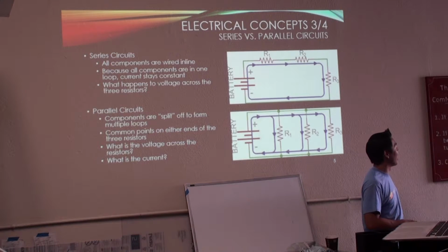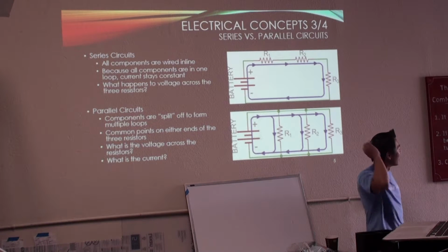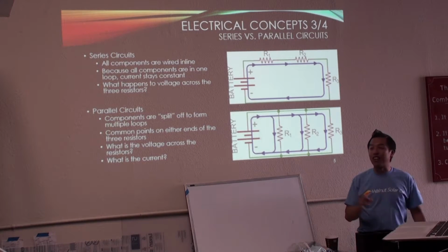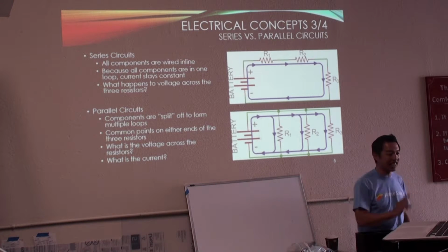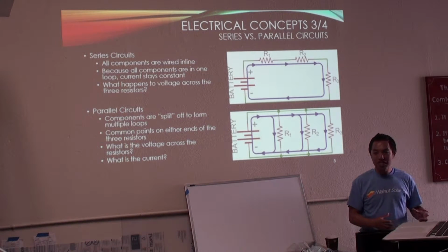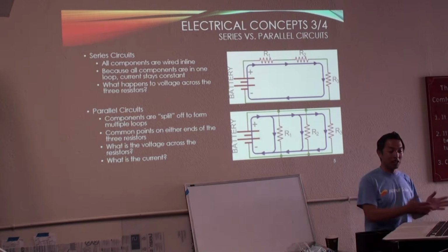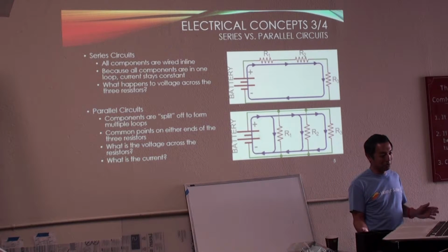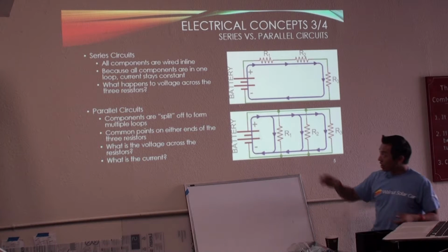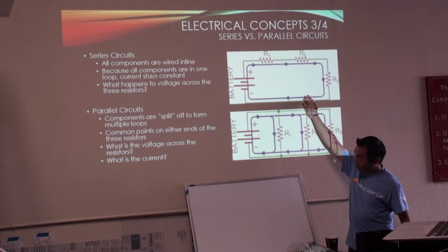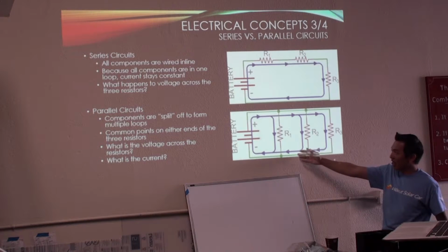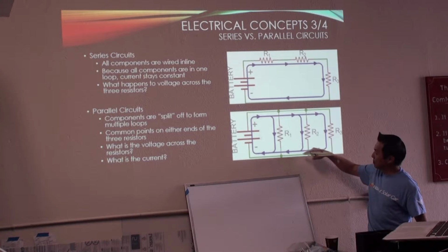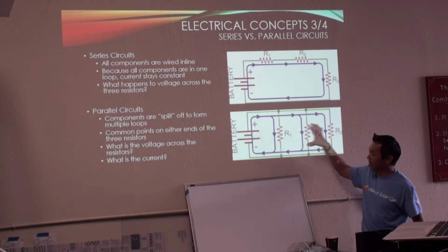If you look at our car, I think they're 4 by 8s. Is that what it is? 4 by 9, I believe. So there are 36 cells on a panel, and then that would give you, because you have to add up the voltage in terms of wired in series, 18 volts. Okay, so that's series. So when you think about parallel then, it means that you are connecting all of these up, and you're splitting components up.